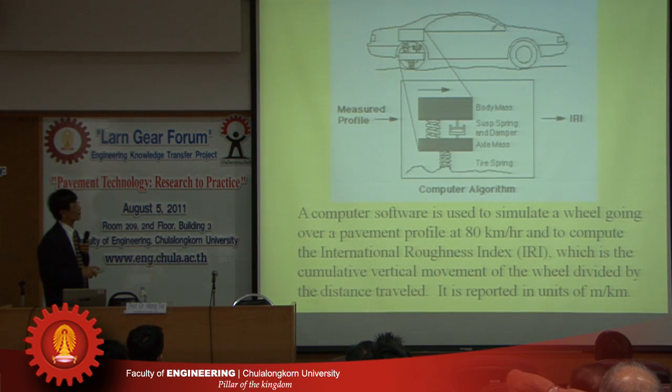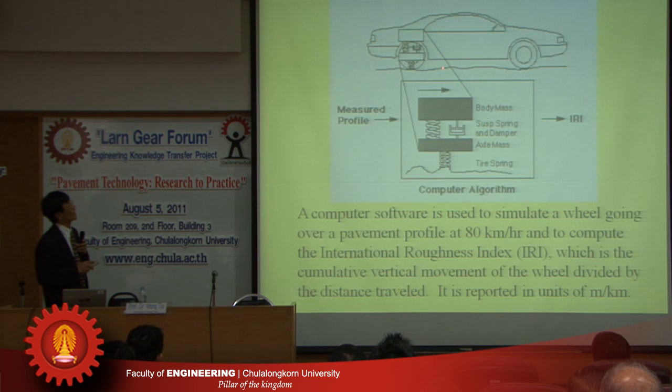Okay. And the longitudinal profile is also used to compute the IRI, the International Roughness Index. The way it's used to compute the IRI is that it takes this longitudinal profile as experienced by the two wheels, and software is used to simulate a vehicle going over this longitudinal profile.